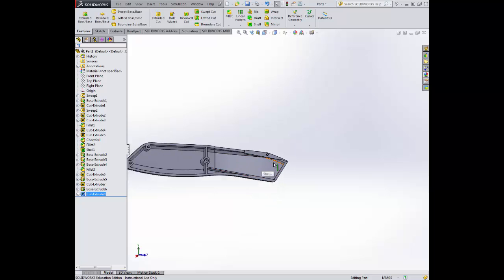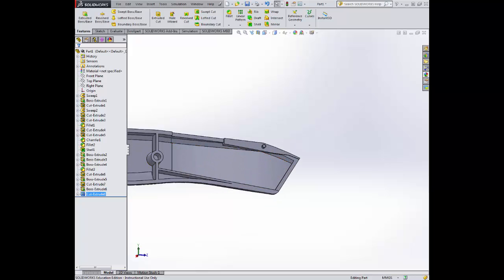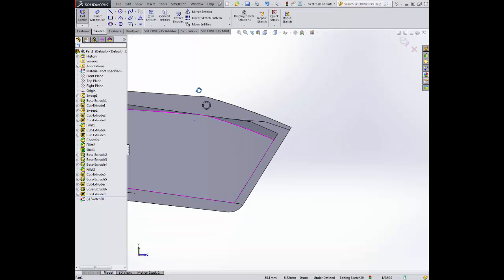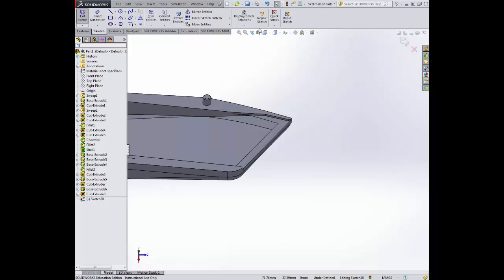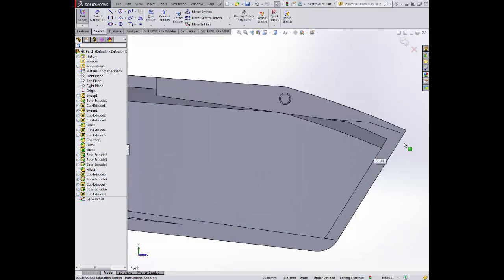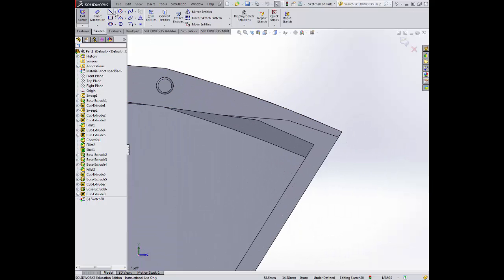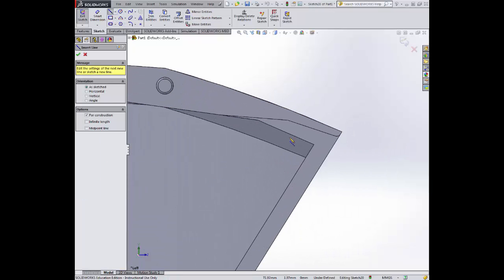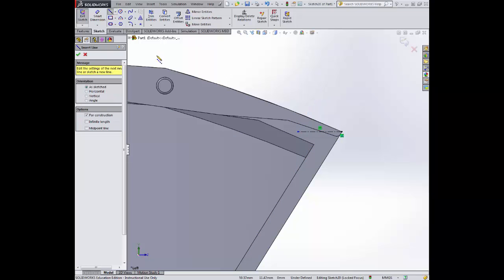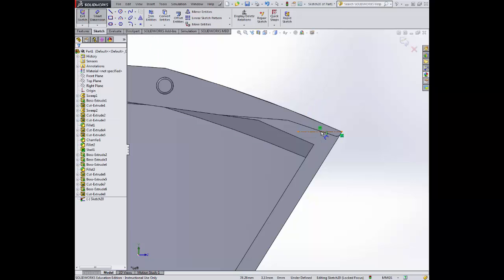Okay, so now the blade will smoothly run out the front. We also have an issue here that the internal components of the slide will also hit this top section here, so we need to actually do a further cut. So similar to the last one in terms of setting it up, cutting it out. So I'm making sure I'm normal to, I'm sketching on the top face. From this corner, this time I'm able to get a straight line. I'm going to smart dimension that.